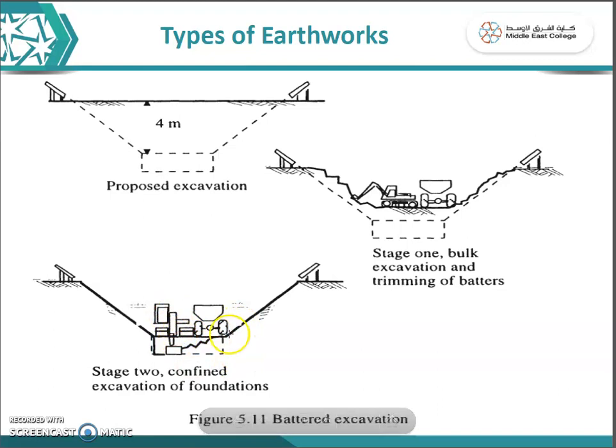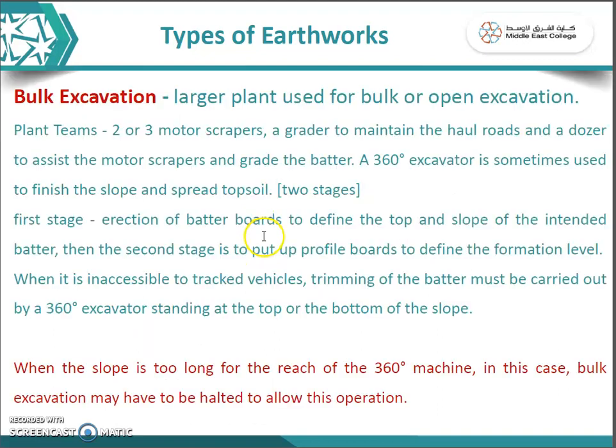So here they started excavating. Here you can see they started excavating again here. This is stage 2, confined excavation of foundation. So this is maintained properly. So the slope has been maintained. So this is deep or battered excavation.